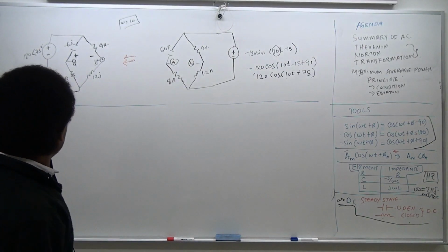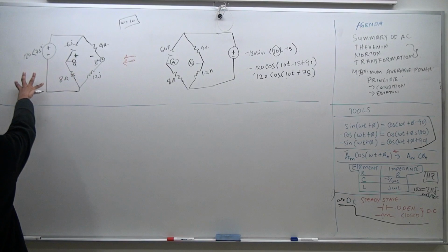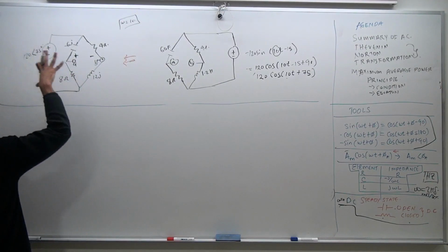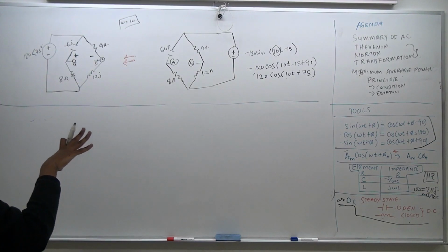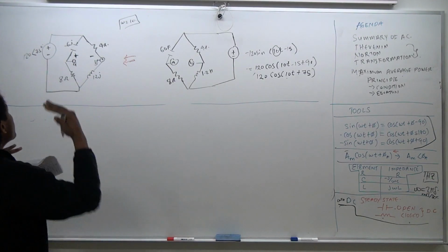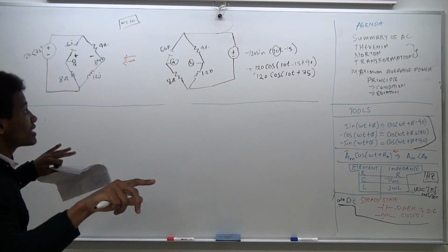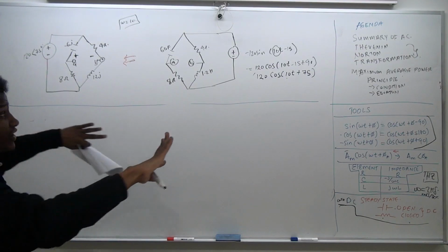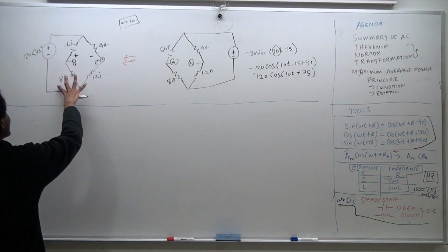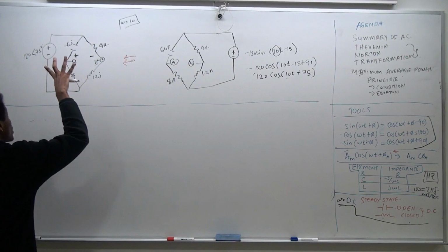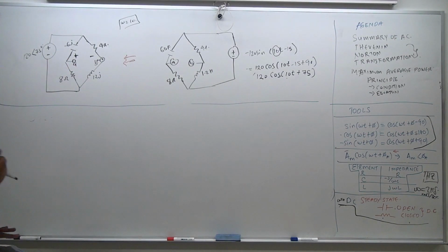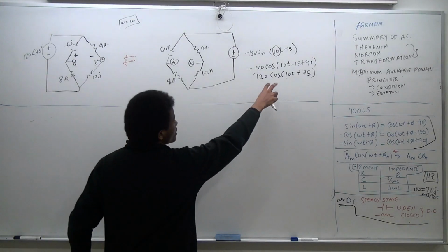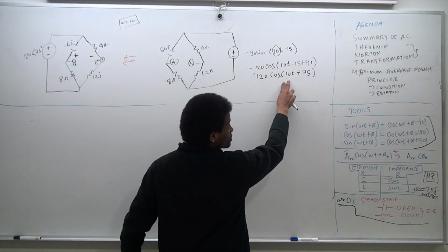Next step. You've reduced your circuit, and right now you're in the phasor domain. Realize this solution is simultaneously tackling the problem whether the input is a cos or a sin, which are orthogonal and not interfering with each other. This is a solution in terms of the complex exponential. You will have to come back to the time domain to solve the original problem, which was given as a cos. A cos is a real function.